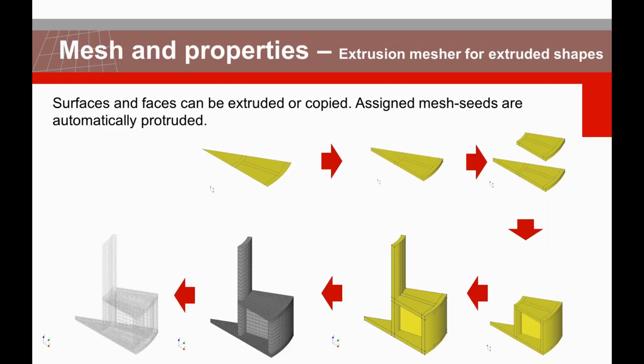At mesh level, we have also enhanced and improved a lot. We added the mesh extrusion feature, which, based on our workflow in DIANA 10 or 10 plus, is based on the geometry. So we inherit the concept of extrusion at the geometry level. Imagine here we have one sheet, a kind of 2D plate element. We're going to extrude that and give it some volume. By this extrusion, we introduce the extrusion feature into the geometry.